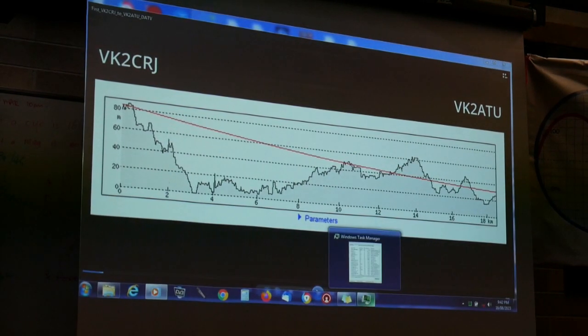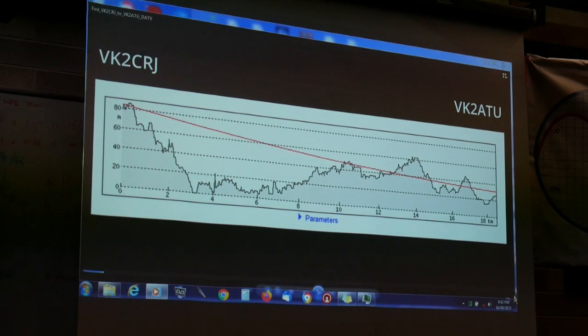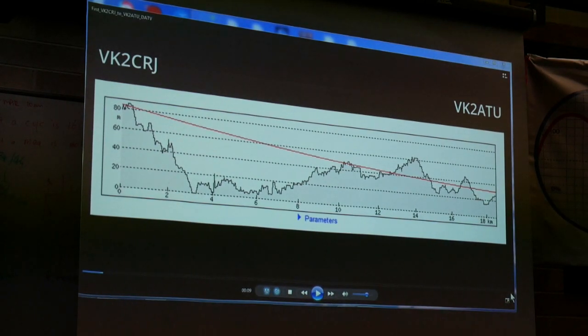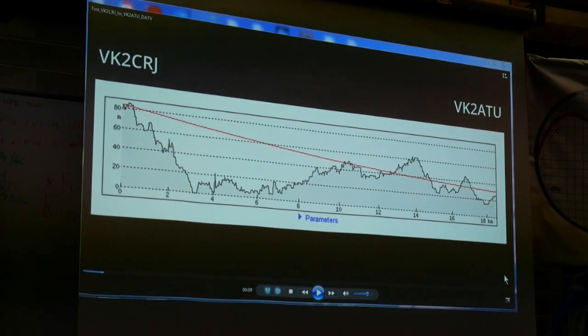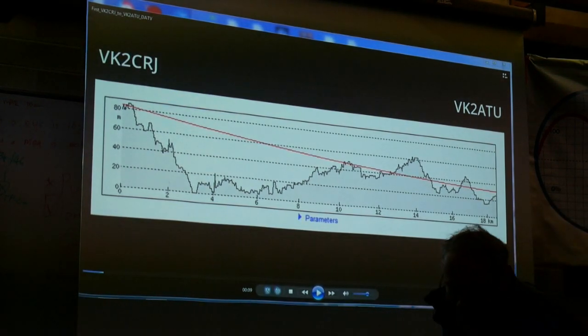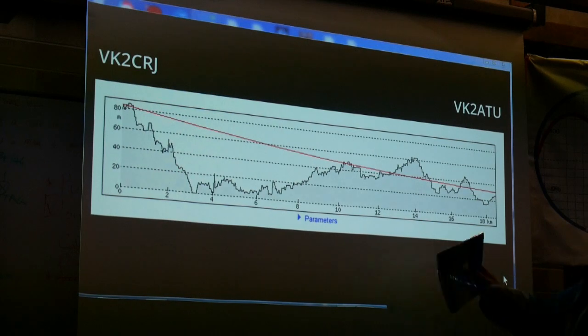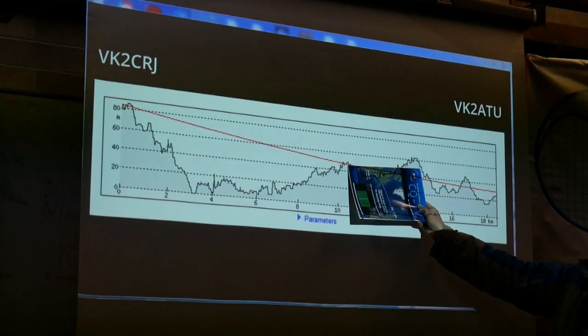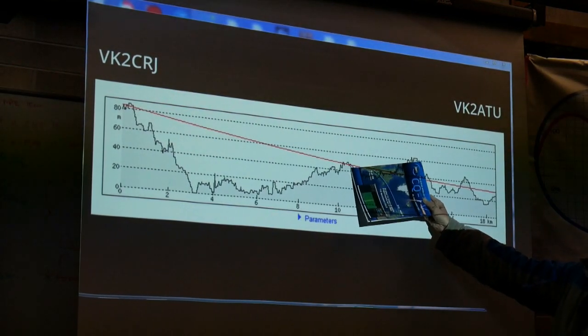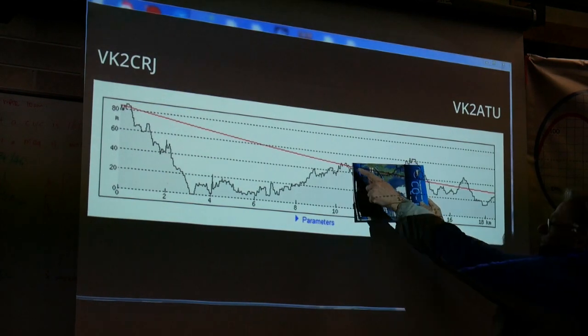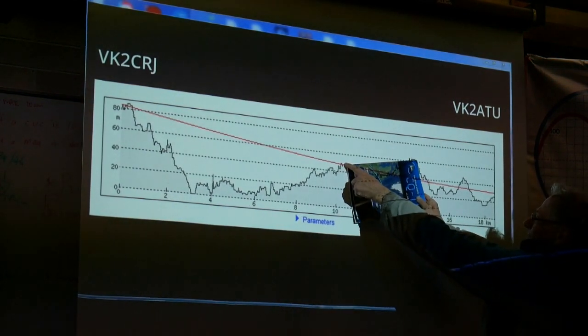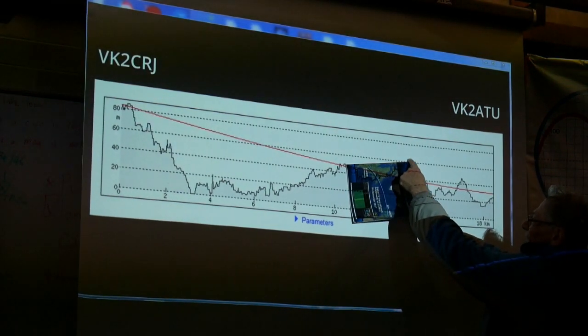If it's hitting anything the right length, anything that resonates re-radiates. Yeah, and that's how signals get around here. The way you can look at this is, when it gets to this hill, if you get some knife edge diffraction and you're going to knife edge diffract over this, you're relying on a signal that is actually following this path to get up to here.